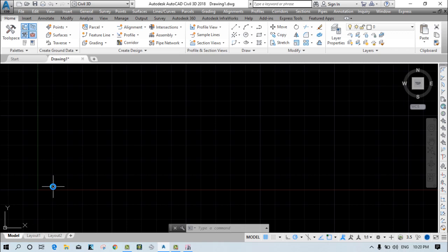So first of all, you need to take a two-dimensional plan from the architecture person and try to draw the center line plan. When you draw the center line plan, it will reflect the position of the column and the beam length, right? According to that, you can also change the orientation of the column as per your concern, because they never go for the column orientation and all. They only provide you the plan.